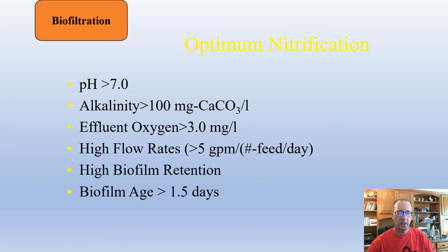going to crash. As you can see, this last line, the biofilm regenerates itself often, and so you need to constantly be aware of how to clean it and how to add additional alkalinity like calcium carbonate back to the water to keep your bacteria really healthy and happy.